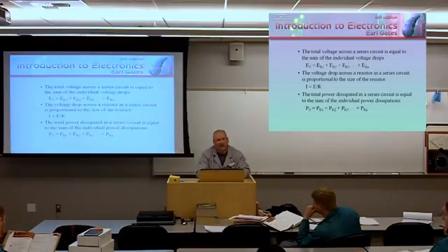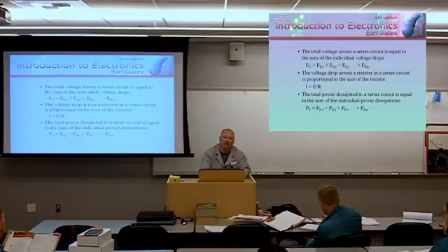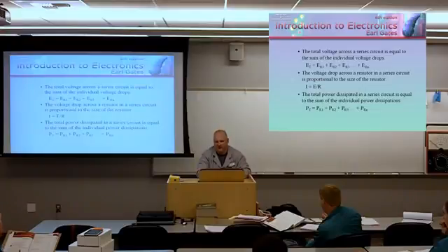The bottom line. You want the bottom line or you want the BS? Bottom line. In a series circuit, the most important thing to remember is current is constant in a series circuit. Period. The second most important thing to remember about a series circuit is also synonymous with voltage divider. When I say series circuit, I want you to think current's constant, and I want you to think voltage divider. That's just how I want you to look at them, and if you're not looking at them that way, you ain't looking at them right.